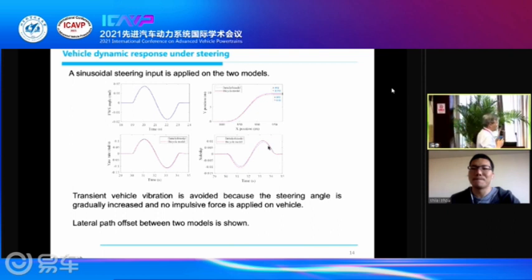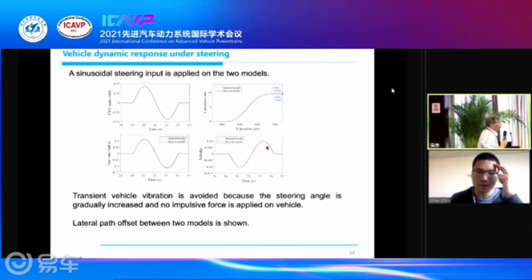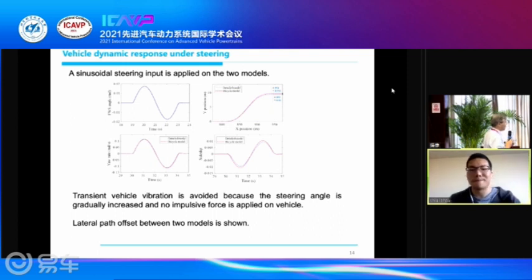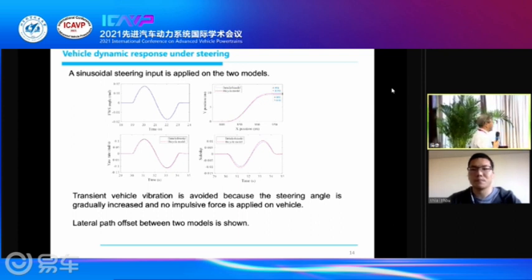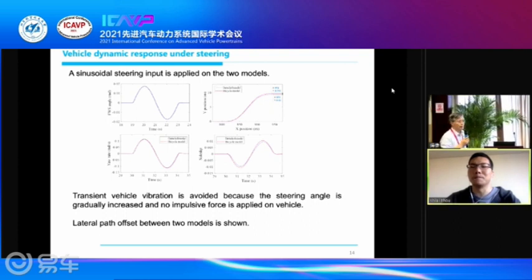When you try to analyze the lateral stability of a vehicle like this, fundamentally from the beginning, you shouldn't really use that bicycle model, because the bicycle model does not have the degree of freedom in rolling. So, if you really want to discuss the lateral stability dynamics, then the half-car model you use should add the degree of freedom of rotation, the roll of the vehicle. So that's pretty obvious. Okay, thank you for your comment.